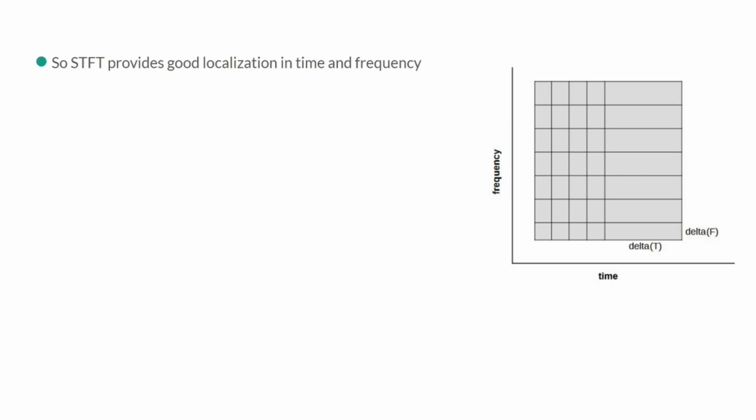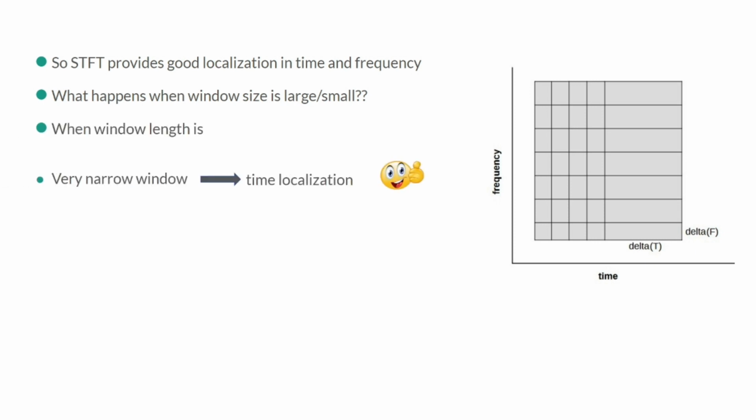For any application, a spectrogram should be precise enough along both time axis and frequency axis. We denote the precision along frequency axis as frequency resolution. The most important factor which determines this precision is the size of the time window which we have taken. If you take a very narrow time window, then we have very few data points, which means we don't have a lot of frequencies. Hence, the precision along time axis will be high, but the frequency resolution will be less.